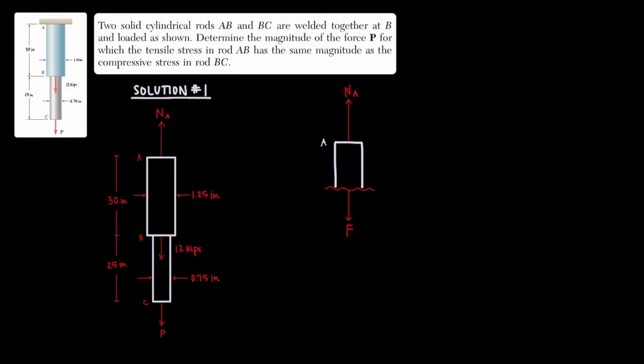Remember, both statics and mechanics of materials are highly dependent on the three main equations of equilibrium. Before we find the stress, we're going to need the equations to find the internal loadings first. Here, we're going to use the method of sections to do that.